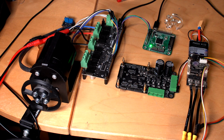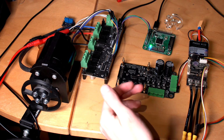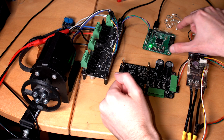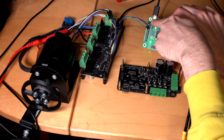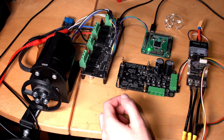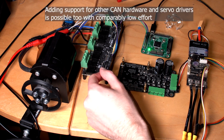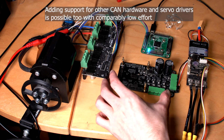These motor drivers, the VESC and ODrive, communicate via the CAN bus. We have a CAN transceiver on board on our FFBoard. This is this small chip here in the corner. And these are the first two functions to use this CAN transceiver as well. And it's quite simple to add support for new motor drivers using the CAN bus in the future as well.